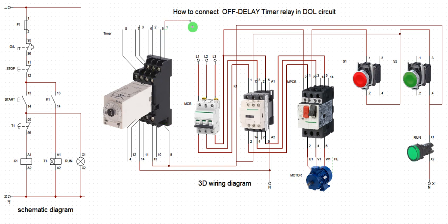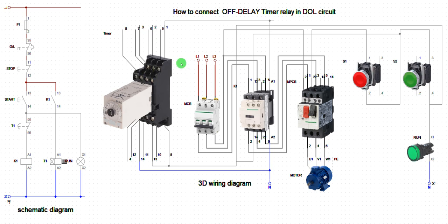Okay. All right. So let me feed the contactor now. I feed my A1 from here. All right. Okay. So if that is done, let me test now. Let's simulate. Just watch the simulation now. Let's put it on. I put my breaker on. Now watch the contactor close. Then watch this one come on. Okay, and watch the timer timing. After 5 seconds, I'll use 5 seconds because of time. After 5 seconds, this contactor will get de-energized. The entire system will shut down.